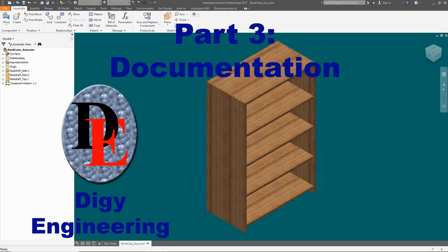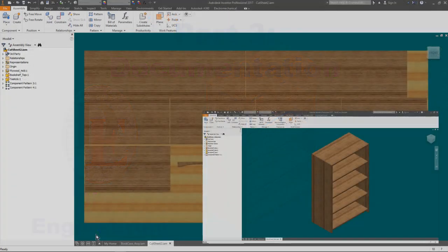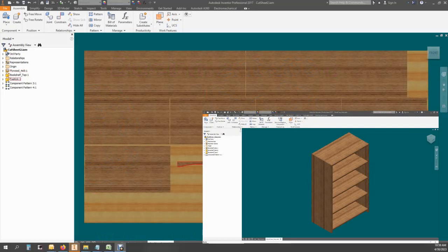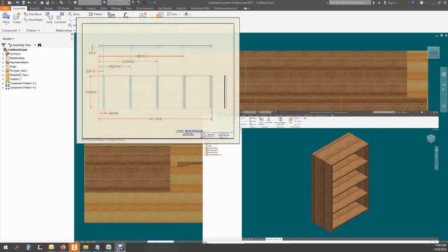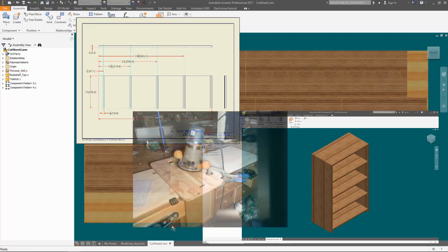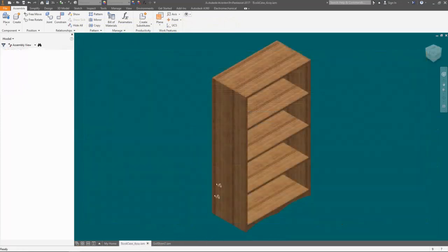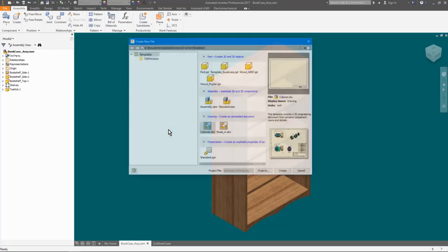Once the cut sheet has been completed, then the dimensions for the parts are validated and it is time to publish the manufacturing documents called prints. The prints tell us the dimensional profile for each part as well as dimensions for the machining processes. This is a simple project requiring only 3 prints since the 2 sides are identical and each shelf and top are also the same. The other print will be for the bottom filler or cove.